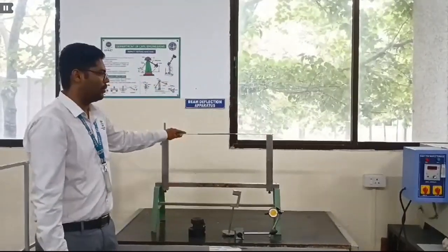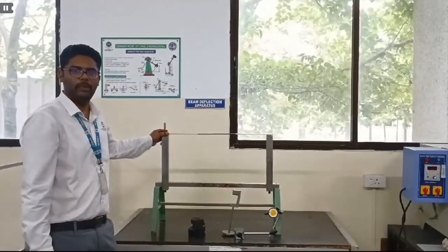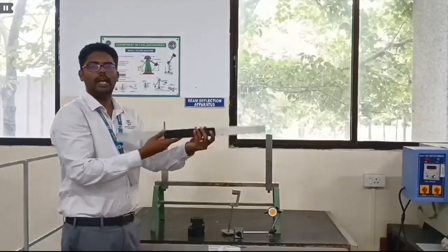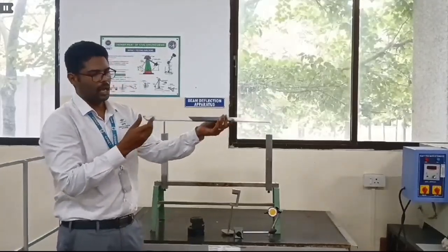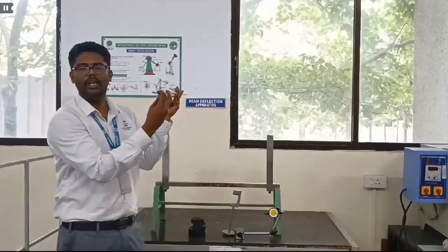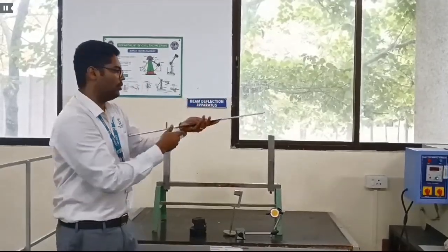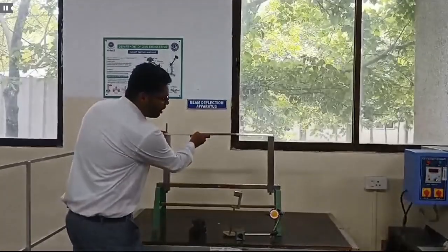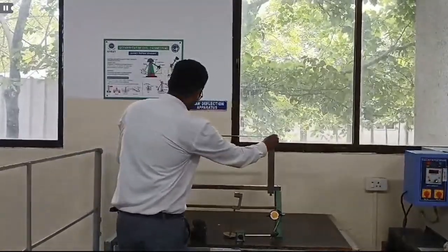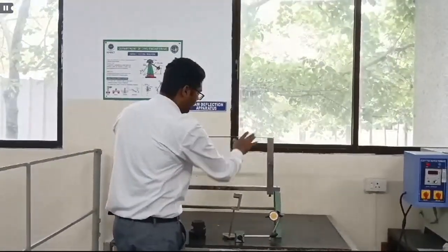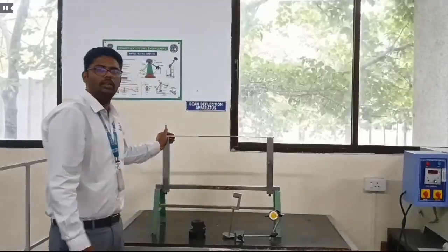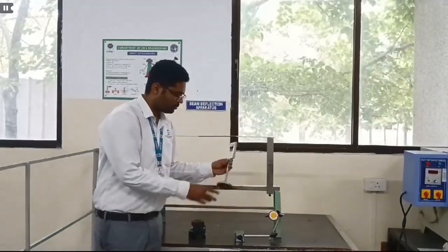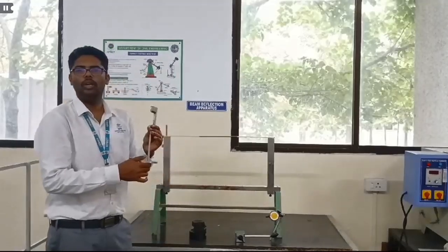Before conducting the deflection test, we begin by measuring the physical dimensions of the beam with precision. Using a measuring tape or a caliper, we carefully determine the length of the beam, ensuring we measure from end to end. Next, we measure the breadth and thickness of the beam. These two parameters are equally important as they directly influence the beam's structural properties.